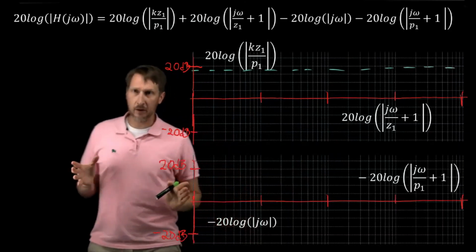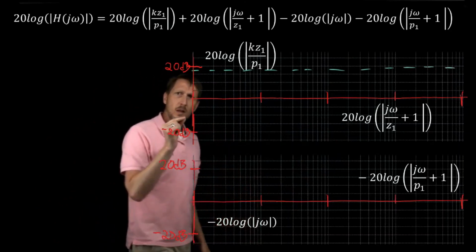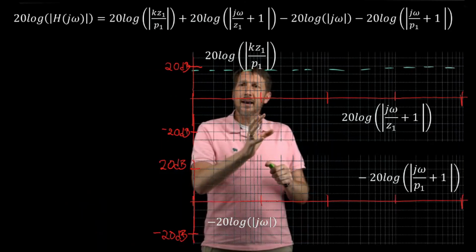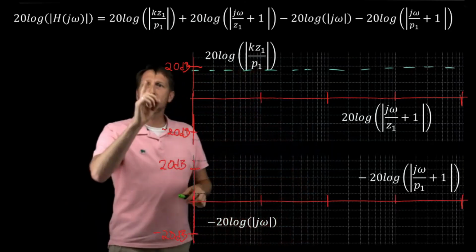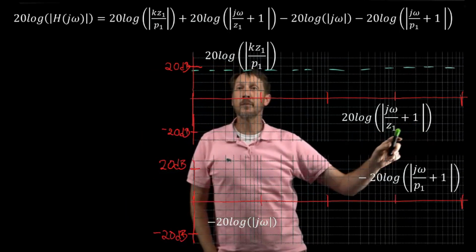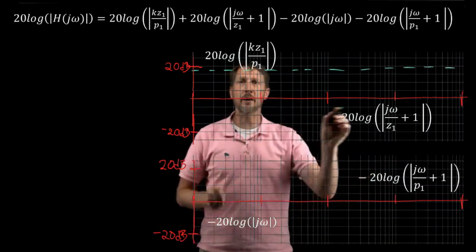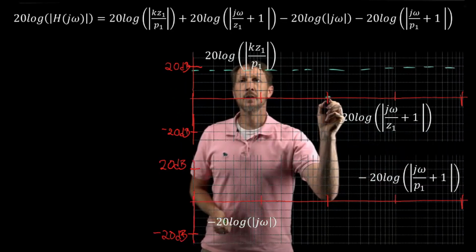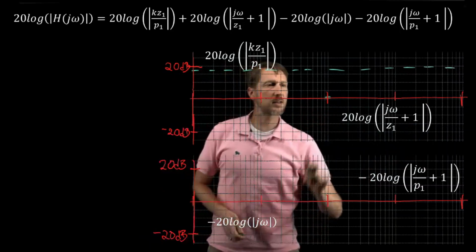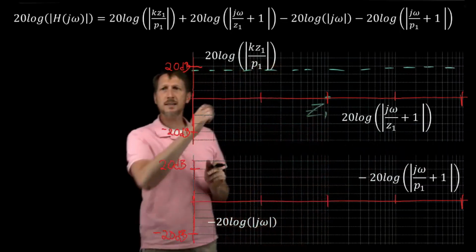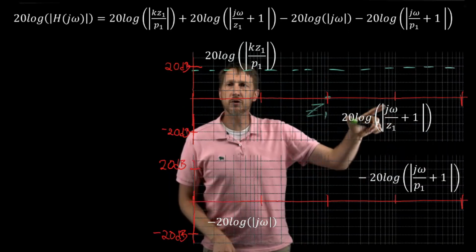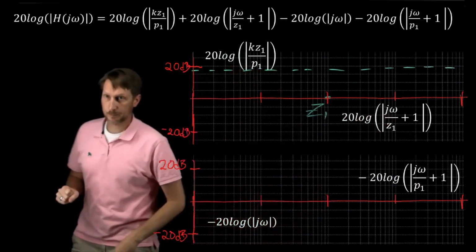So the very powerful thing about the Bode plot is that we can use the plotting tools to not have to go into the details of what it is, but we look at where this ratio is equal and then starts to overcome. So depending on where the 0 is at, we're going to put a point where the 0 is at. And let's say, for instance, 0 is right here. The Z1 term. Okay, so let's say Z1 is that omega value right here. This is the omega value that's going to turn this ratio into a unity, into a 1.